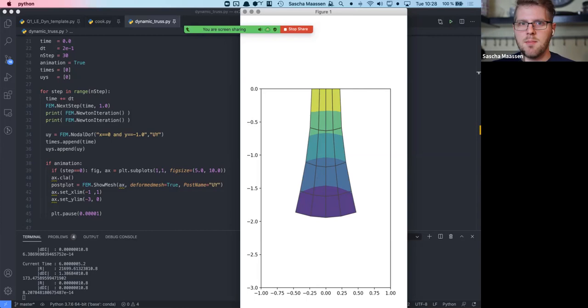So in this dynamic analysis, we can see that there's some inertia in the system due to the initial elongation. And now you can really use the blueprint of the single mass oscillator problem. This inertia is transferred into strain energy and back to kinetic energy. And so you see kind of an oscillation here in this two-dimensional oscillator bar as well. So once this simulation is done, I don't see anything further. Also notice that the residual is numerically 0, which is important as said before.